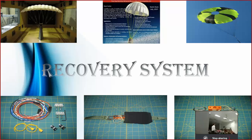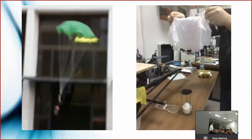Let's talk about the recovery system. We have many things to use. We can use parafoils, we can use a parachute or a hold parachute, or something called a 3D parachute. In the photo on the left, it's our CanSat falling down with a descent rate using a parachute, while on the right, another team does a test for their Texas competition parachute.